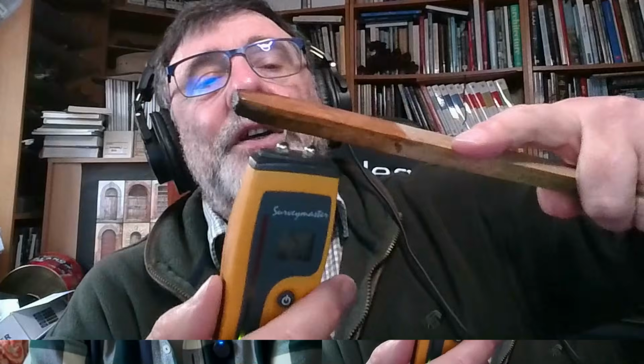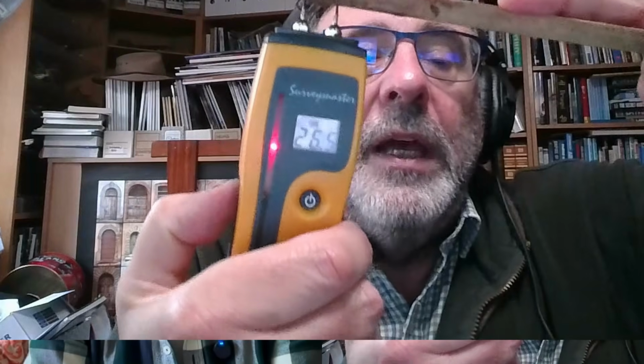So anyway, going back to my piece of fence post dunked in my water here. It's been in the water a few minutes now. So that end, as you can see, is nice and wet. I go back to the dry bit and it's still reading 10%, what have you. Now we get to here and all of a sudden it's gone up to 25% there, near the end. And yeah, 27, 28%. Sorry, I'll reverse this round. There you can see it's in the red.